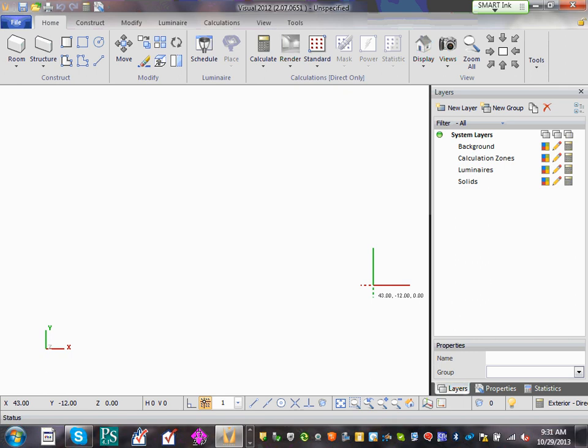What this does is it just takes direct light. There's no reflectances involved. In the interior one, we want to factor in our walls and our ceiling. It'll be more important when you're looking at a big open office. I've seen some linear direct-indirect fluorescent in some offices, or those will be suspended. You're going to want reflectances in that room because it's going to make an impact on your lighting. For exterior, you're just calculating at ground, and it's just direct and not reflected.